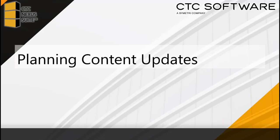Just reprocess it. As you saw with that door that I processed earlier, it had an older edition of that door from 2018 and 2020, and I added to it today the Revit 2023 version. And that Revit 2023 version, in my case, is going to automatically upgrade once that process kicks off. But all you've got to do is, when you make an update, throw it into the CMS and process it. If the path changes, it'll update the path. If the content inside the family changes, it'll update that data for that version and all future stuff.